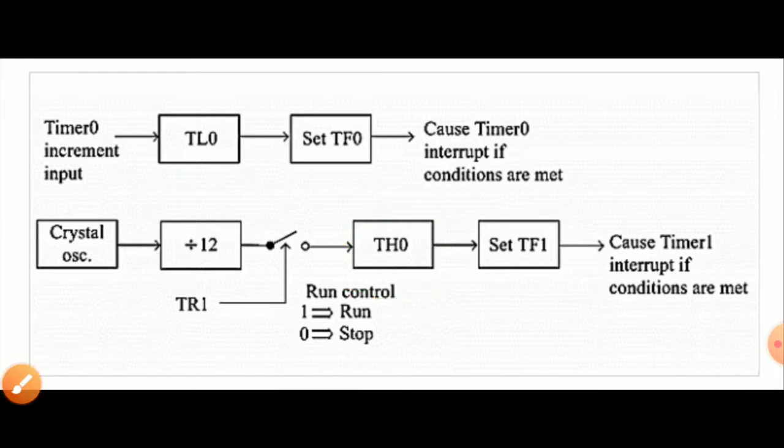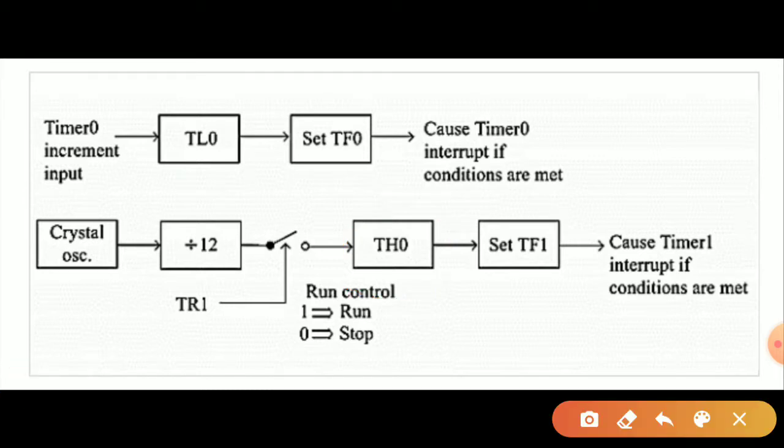Here, this timer using the TL0 can be operated as a timer or counter, and it uses the control bits of timer 0. That is, it can be started and stopped by TR0, and the overflow flag that can be set or cleared is TF0.